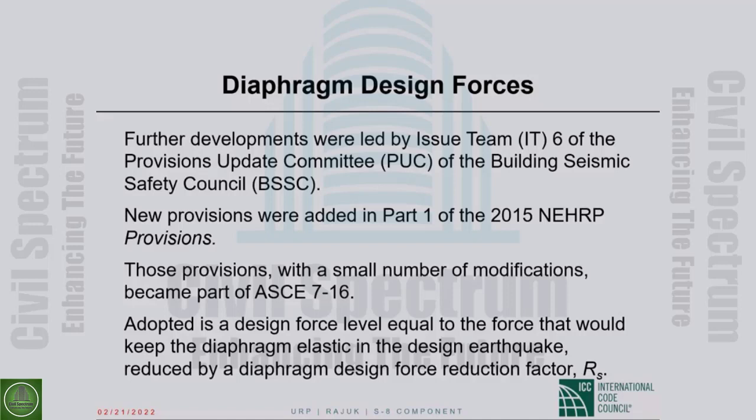The structures will need to deflect freely with whatever you have installed in place. So the gap has to be maintained. You cannot let it be filled with debris or whatever over the years, because then you don't have a separation.